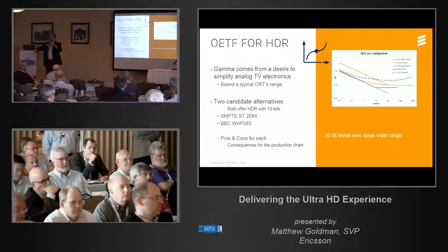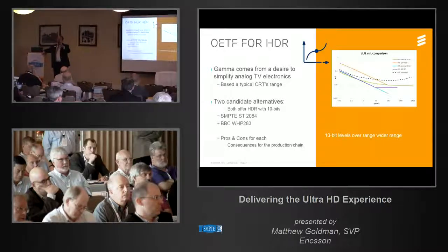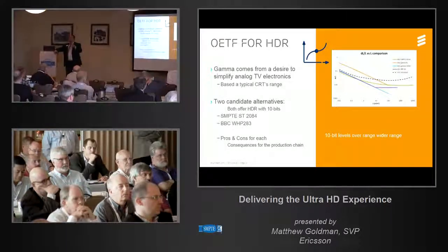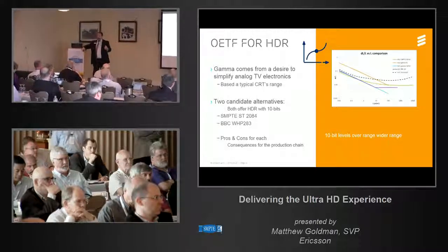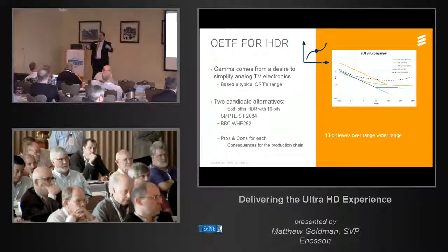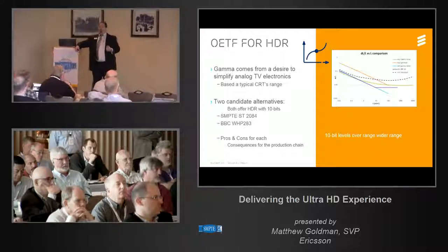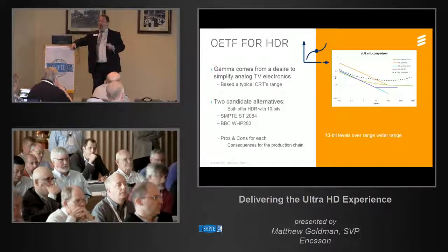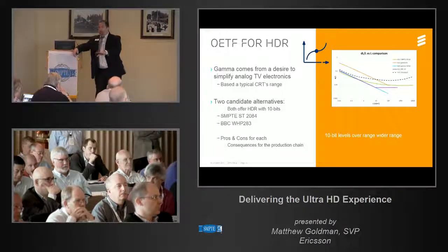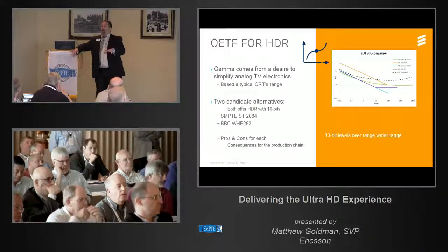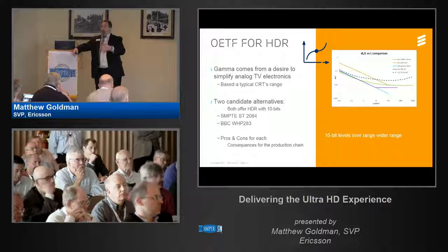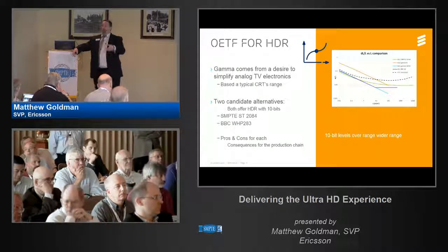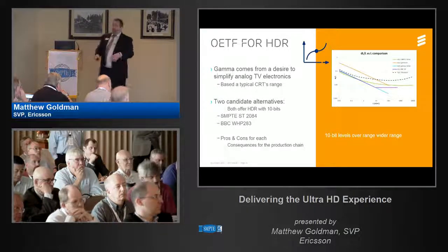Your eye is not as sensitive to color as it is to brightness, so to save compression bandwidth, we found we can throw away 3/4 of the color, again to the home only. If we compress it once and throw away 3/4 of the color, it's better to use those bits to compress the brightness instead, and that's the 420 that's commonly done to the home. Everything is 420 to the home.